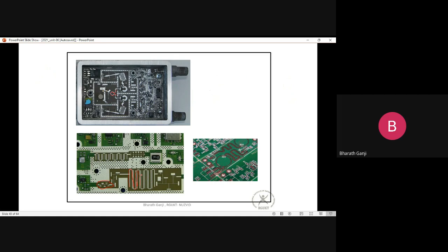You might say there is no inductor and capacitor here. Yeah, there is no need on a microstrip. You can actually use open circuit and short circuit transmission lines as inductors and capacitors, and you can design those filters. So designing a filter or designing circuits on microstrip lines is a kind of art.